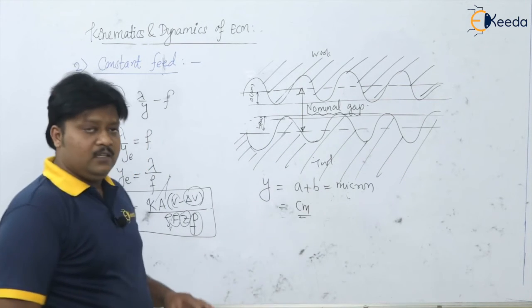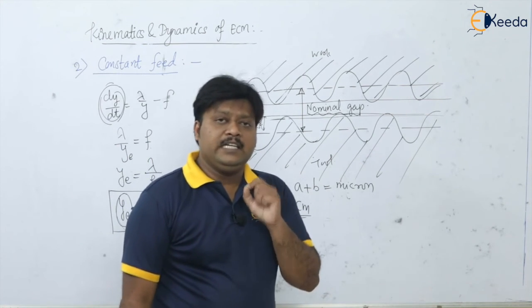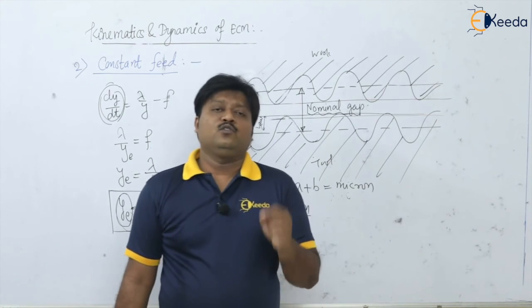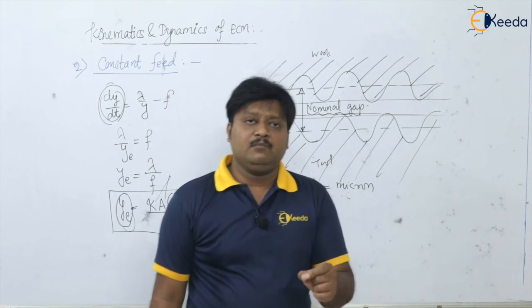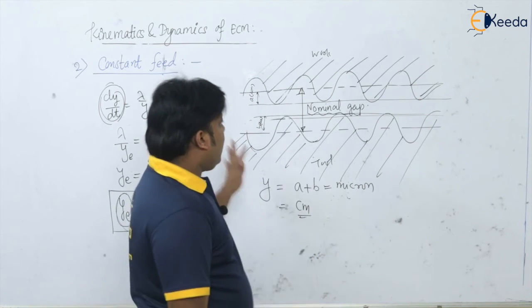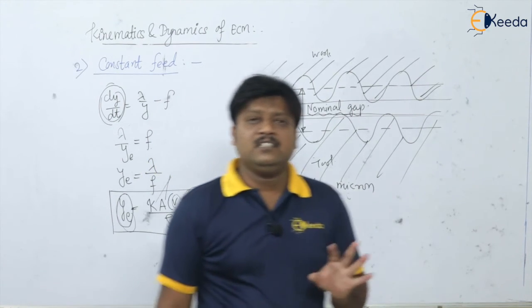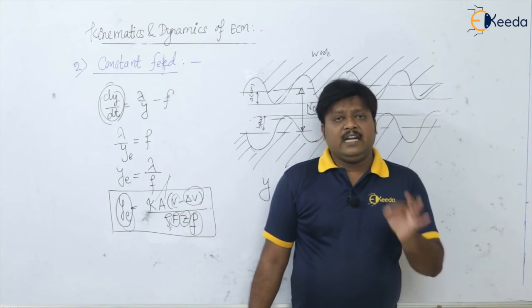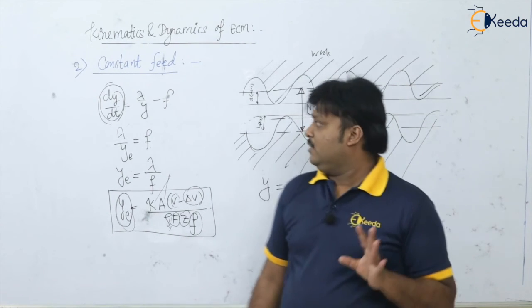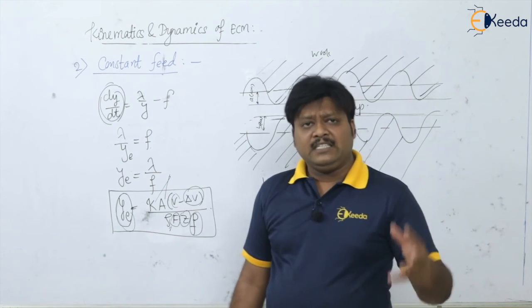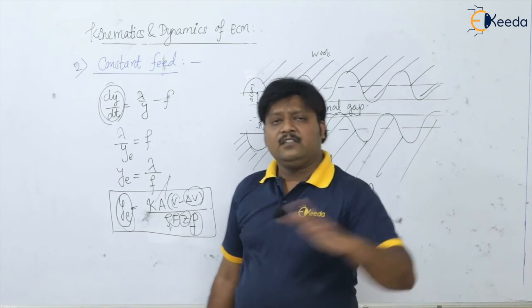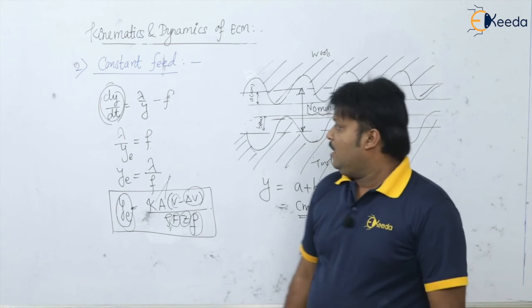So please remember, all the electrochemical machining formulas I have given are in CGS. So the length in centimeter, weight in gram, and time in second. So try to have all lengths and velocities in centimeter per second, isn't it, and weight in grams. And if they are asking to convert, say they are asking in millimeter or in minute, we can convert later.